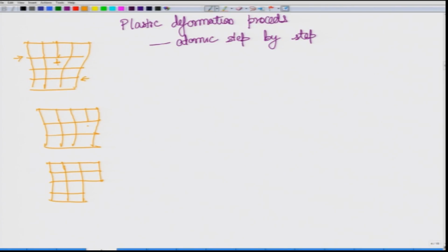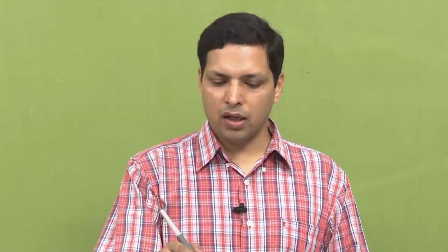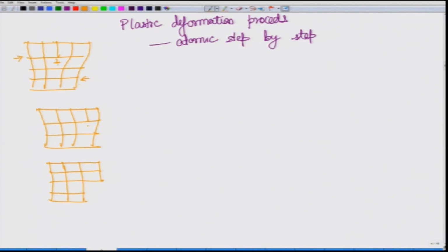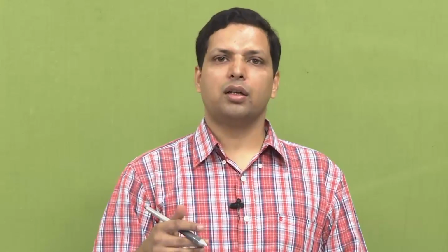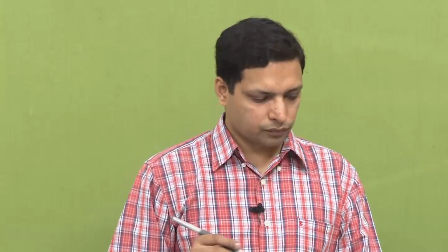And you can see that you do not need to shear the whole plane, only one line of defects is being broken and being moved, and for that the stress required would be much smaller. In fact, even this model will have more as we develop more understanding. Even in these line defects you develop steps which are called kinks and jogs. Those kinks and jogs are what lead to the movement of this whole dislocation. So, the real stress required is even further lower than what we know.